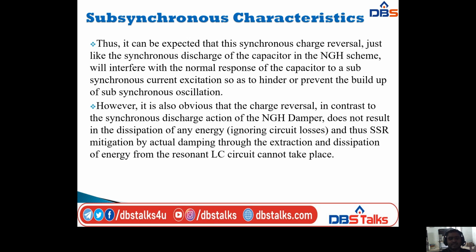However, it is also obvious that the charge reversal, in contrast to the subsynchronous discharge action of the NGH damper, does not result in the dissipation of any energy, ignoring circuit losses. Thus SSR mitigation by actual damping, through the extraction and dissipation of energy from the resonant LC circuit, cannot take place.